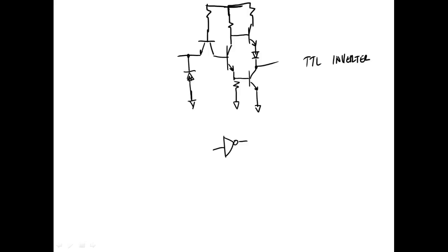What's important to know is what? A high gives me a low. If it does not give you that, you don't go in there and replace Q1. You replace the what? The IC. But what we have to do is look at this so I can understand what's a legal high and what's a legal low. TTL operates on plus 5 volts.